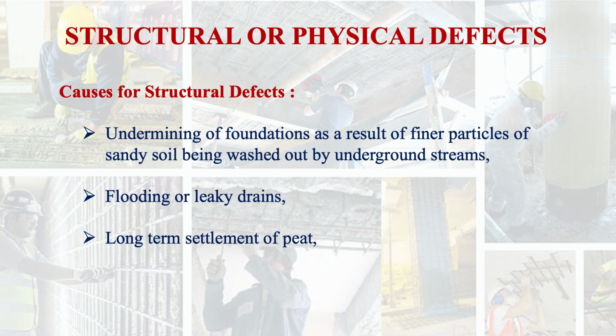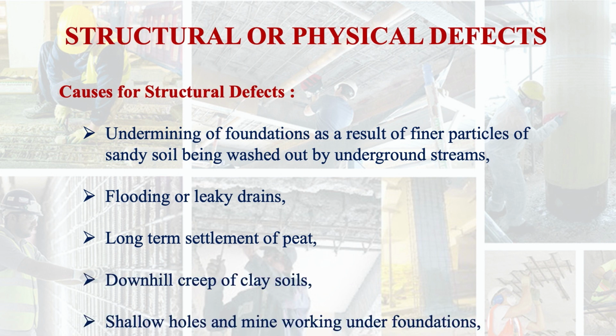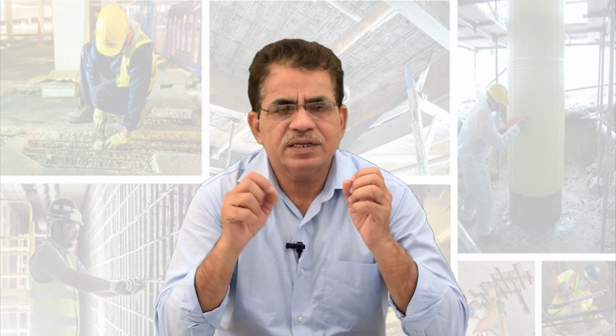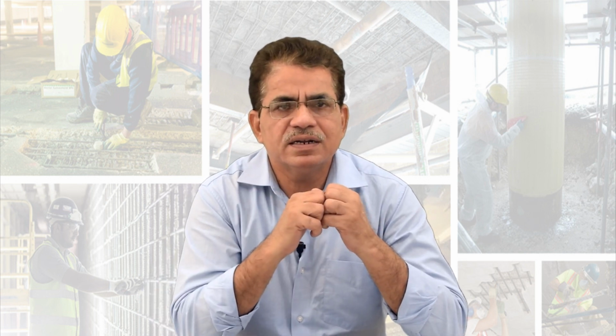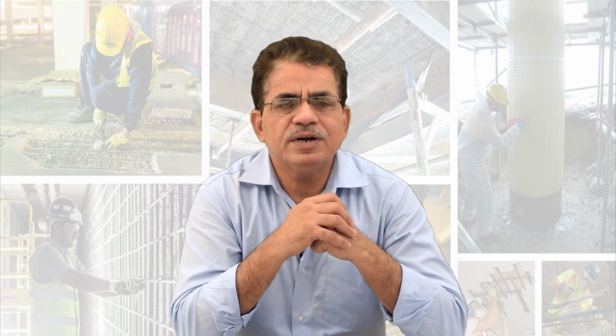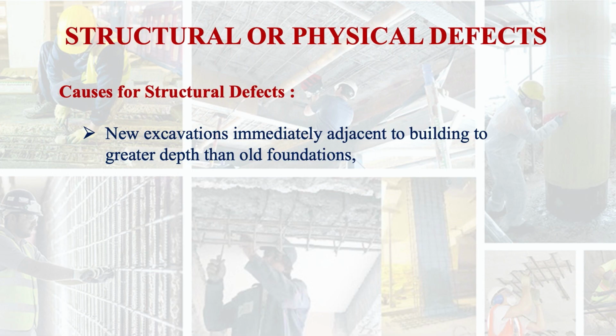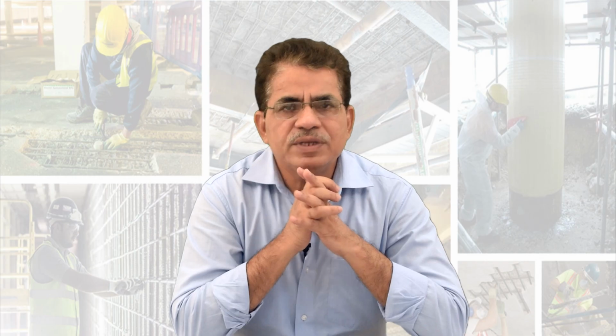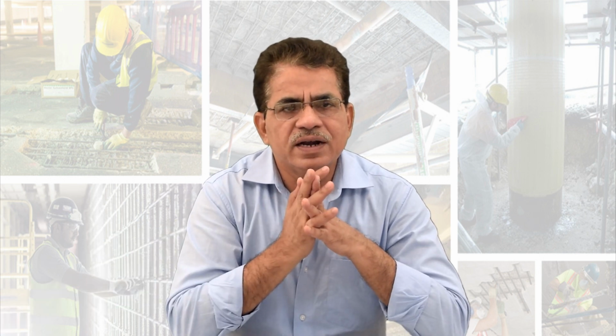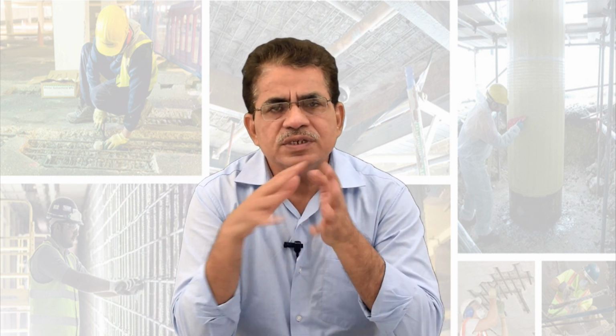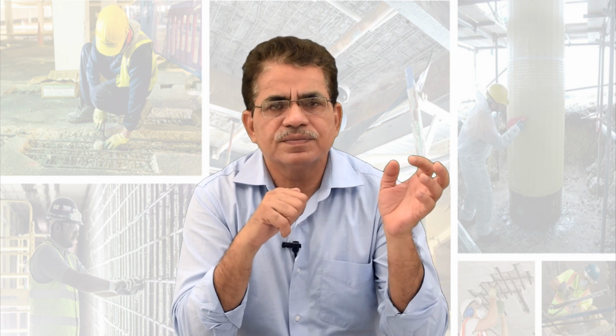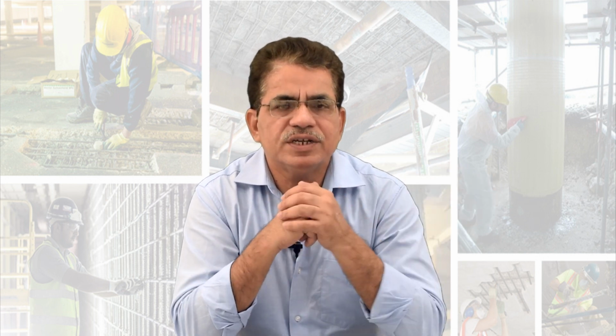Then long term settlement of the peat. Another problem is downhill creep of clay soil. Another is shallow holes and mine workings under the foundation. If some holes or mine formations are there under the foundation, then certainly settlement of foundation will occur. New excavations immediately adjacent to the building to greater depth than the old foundation. That means some new construction is going on, and if the excavation is deeper than the existing foundation, then there will be an effect on the old foundation.